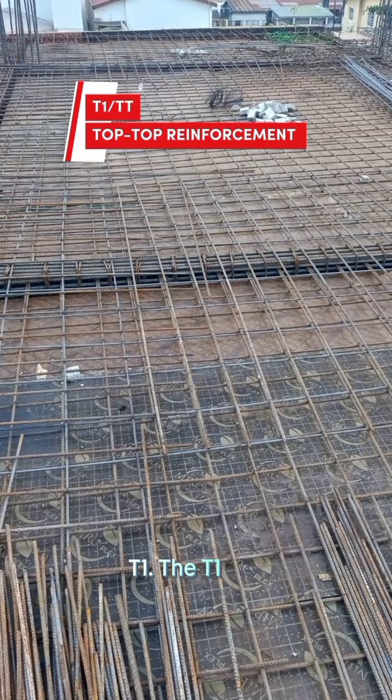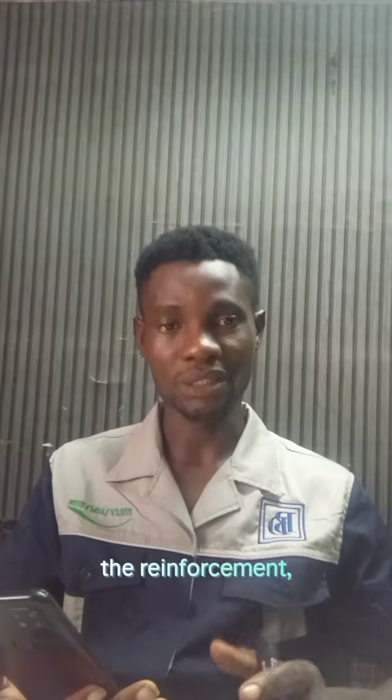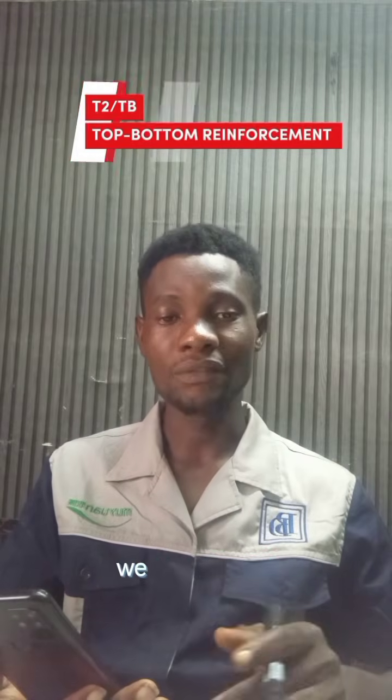The T1 can also be called top reinforcement, that is TT. It is the topmost reinforcement in the slab. The reinforcement runs over the beam, over the reinforcement of the beam, from one panel of a slab to the other panel of a slab. That is the T1 of the reinforcement. That's the T1. Then we have the T2.